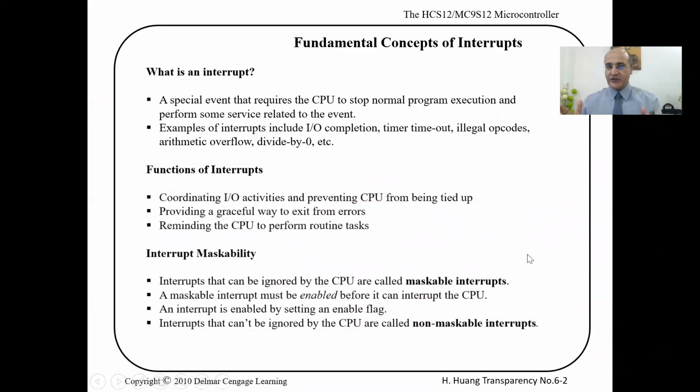Interrupts are opposed to something called polling, and we usually use them to service the things that need the CPU. For example, in our microcontroller, the CPU has an infinite loop, right? Let's assume we want to write code to do the following. I want to check if button 1 is pressed, and if it's pressed I want to turn on the red, green, blue LEDs. If button 2 is pressed, I want to increment a counter displayed on a 7-segment display.